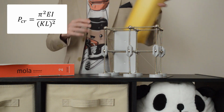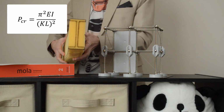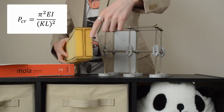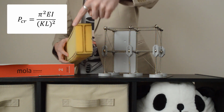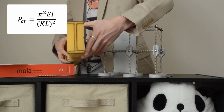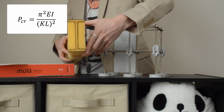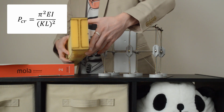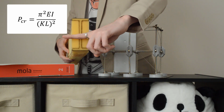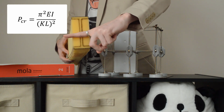So when I look at the cross-section of this piece of foam, I should notice that there are some axes that I can draw through the center of this shape that would yield larger moments of inertia or larger resistance to bending than others. In fact, the largest possible moment of inertia I could calculate would be about this axis.